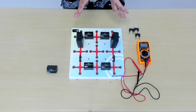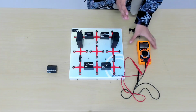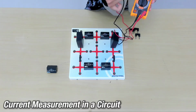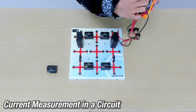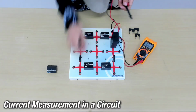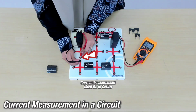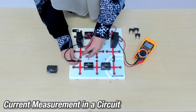As the closed single loop circuit is complete, it is time to measure the current and voltage using the digital multimeter. Okay, to measure the current, the circuit must be arranged in series. First, turn the dial on the multimeter to the current reading. Then remove the connector and insert the probe into the hole on the breadboard. And yes, the value of the current will be displayed. Okay, remove the probe.